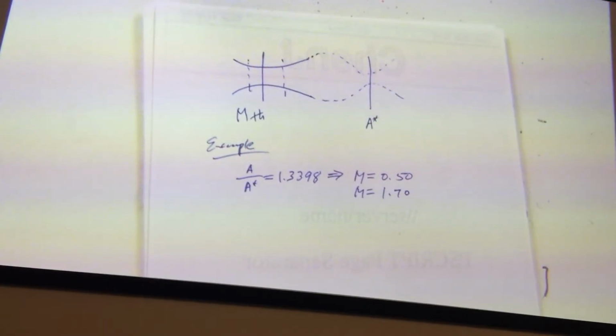So when you expand, you are pushing the gas to higher speed. And if you have higher speed, you have more momentum drop, then you have more propulsive force, right? Now, if the gas, or in this case, we are talking about a supersonic inlet, comes into the combustor with a shock wave, that means the stagnation pressure will drop. So you lose the ability to expand because your pressure can only be less than your stagnation pressure, right?